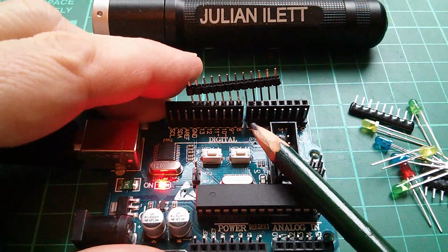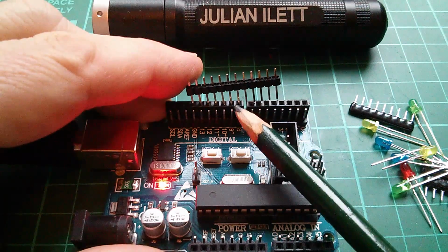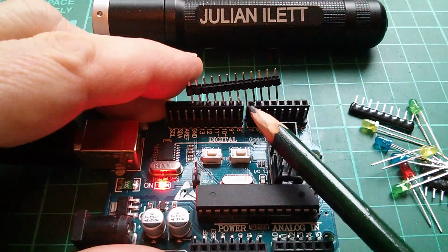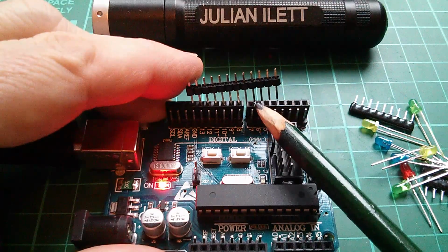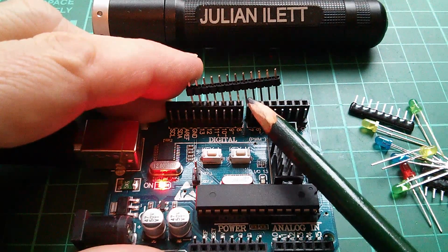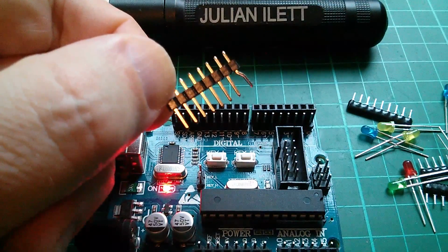and 7. Well, that's a nuisance because pin 7's on this other header, and the gap between these two headers is that awkward 1.5 tenths of an inch, or 150 thou. So the pins don't line up with this second header. So what I'm going to do is break it off here and bend this pin out a bit so it spans over that unusually large gap. So it's a bit of a fudge.